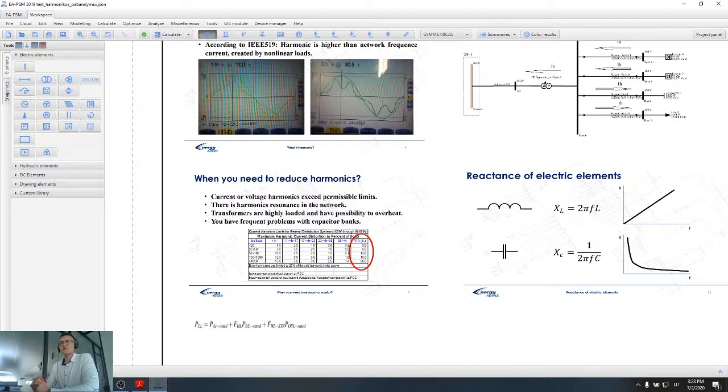During normal operations, other loads are linear. However, for example, a transformer, if it is saturated, can also generate high frequency harmonics. Also, one more type of loads is power sources. So all the computers have power sources, and basically those power sources also generate harmonics in the electrical network.